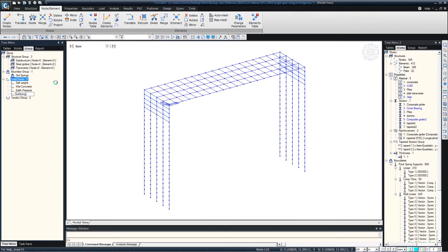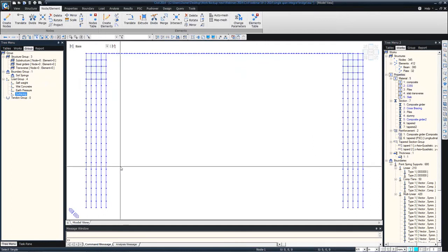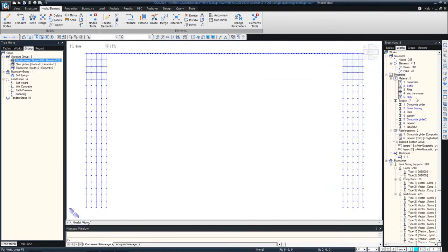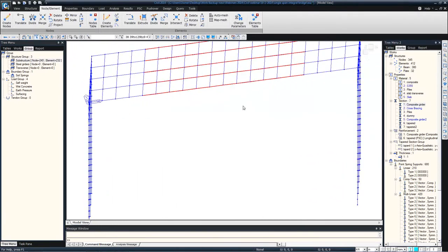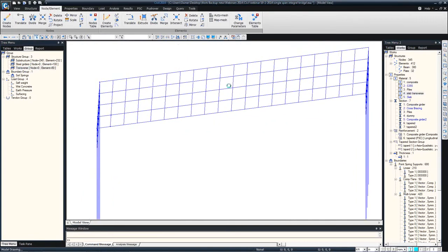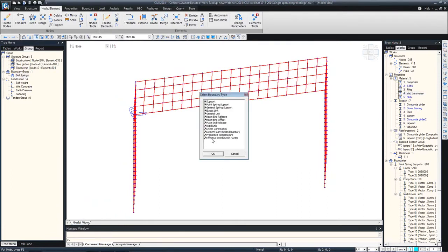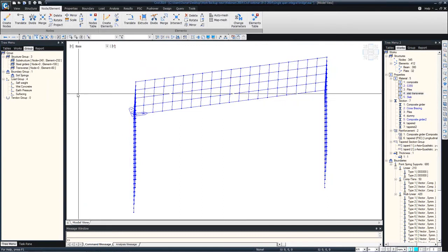So that is also another way of applying earth pressure and surfacing. Okay. Now quickly I'll assign different types of elements to groups. So I'll start with the piles and abutment first. So just quickly copying all the piles and abutments and drag and drop into substructure. All the steel girders, so double click on the composite material and drag and drop into steel girders, and double click on slab transverse, drag and drop the transverse members. Then select everything, drag and drop soil springs to include all the boundaries in the structure into the soil springs group.